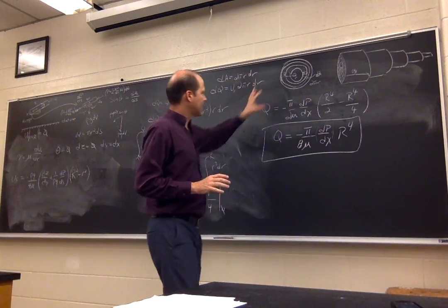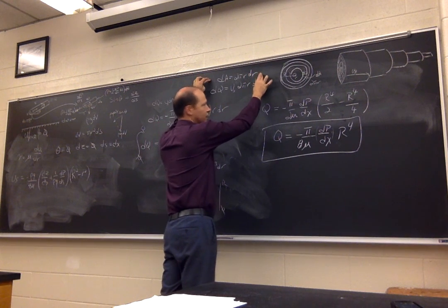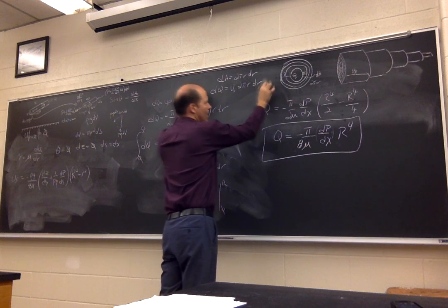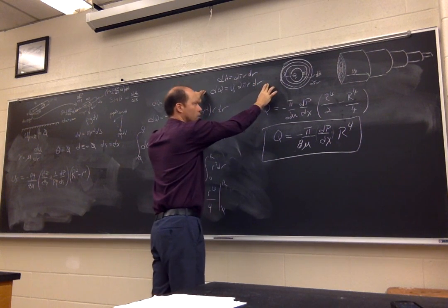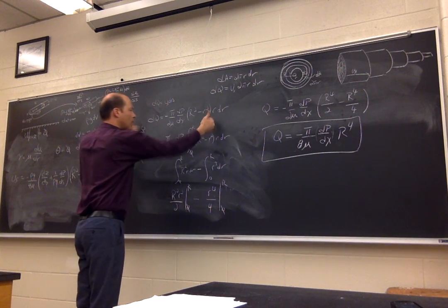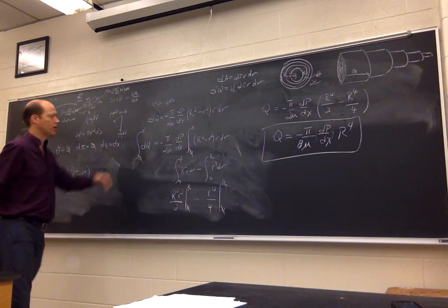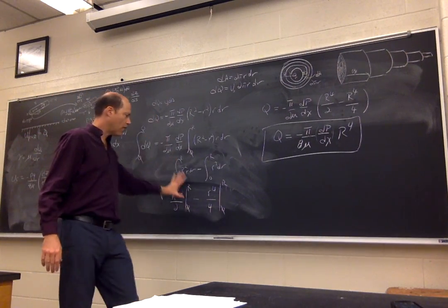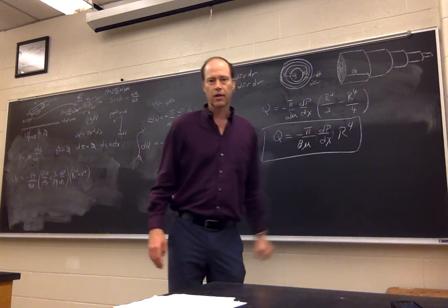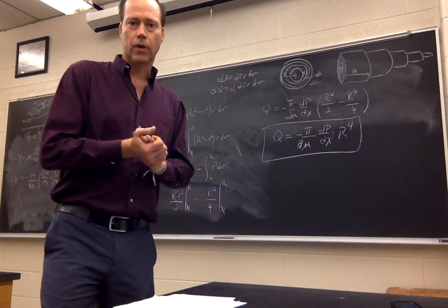Then, again assessing the geometry and what the cross-sectional area means in terms of that velocity cross profile, and what discharge must be in terms of that profile, we can sum up all the little pieces in discharge because we know what our velocity cross profile must be. We integrate it up, and we find out that it's related to the fourth power of the radius of that pipe, and that is Poiseuille's equation.